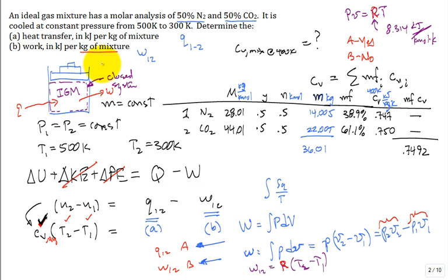Because we have two equations, P V bar equals R bar T. That's a great equation, right? But it's written not on a mass basis, it's written on a kilomole basis. And that R bar is the universal gas constant. This equation right here, PV equals RT, is written on a mass basis. How did you jump back and forth between them? Took this and divided by, true?